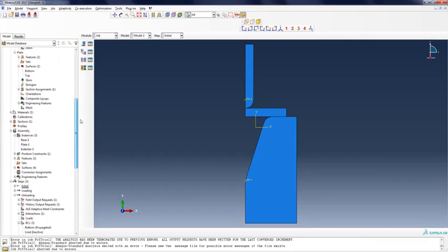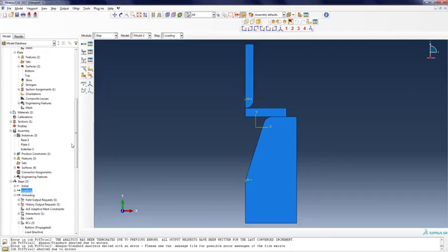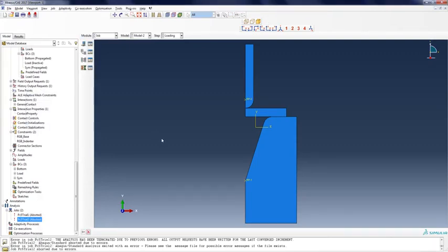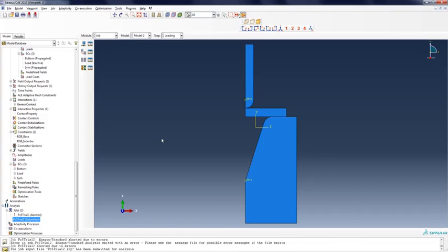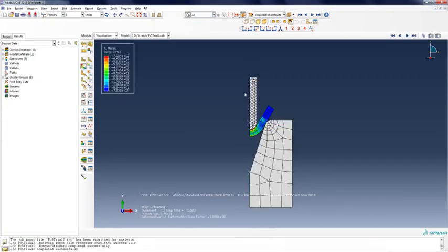Indeed, this is not yet a convergence issue, so we go to loading. We increase our increments. Let's be a little bit braver. So now we have 10,000 increments, should be sufficient. And we have completed the job. Result. Yes, so now we run into full increment, and you can see that it bends quite a lot downwards,